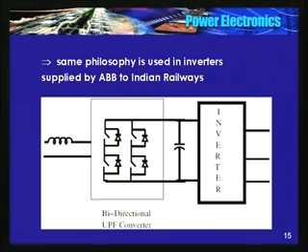See here, we have studied this converter. We call it a unity power factor converter. I am just showing a single phase case. We have 4 controlled switches with freewheeling diodes, a DC link capacitor and an inverter. So this is nothing but a bidirectional unity power factor converter.